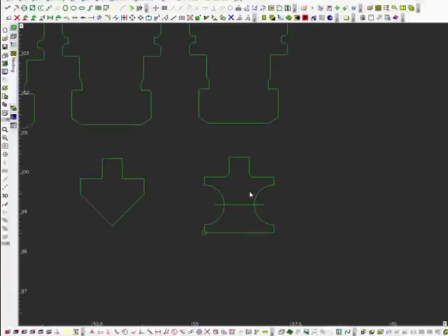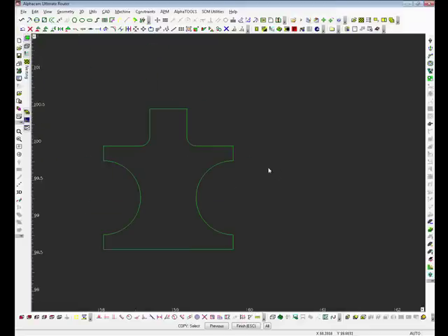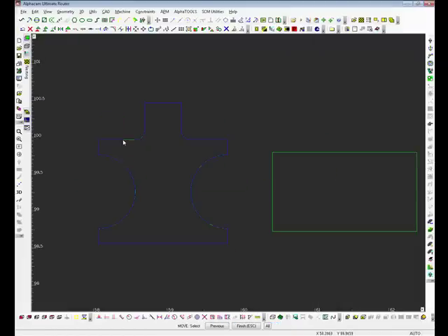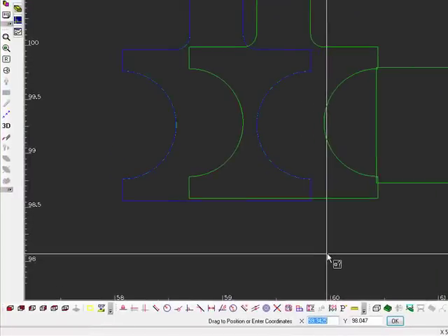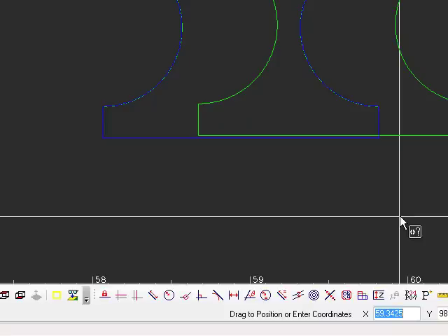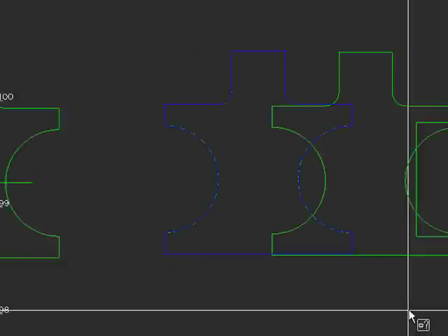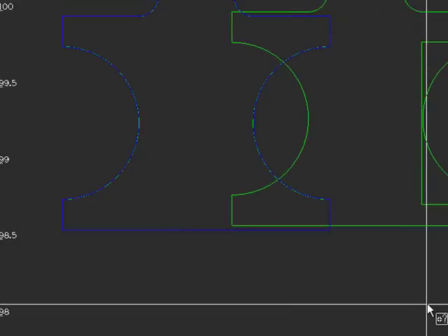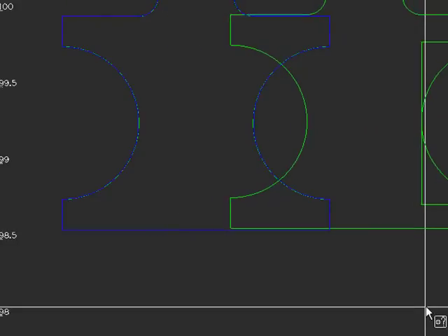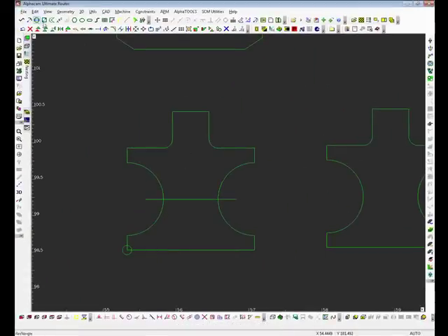Let me go ahead and exemplify this. I'm going to copy this out, and I'm going to put it on the right. And this rectangle that I'm drawing represents the material that I actually want to cut. You see, if we didn't have that line, the tool would always act right there, right on the edge of the material. If I put the line in the center, like we see over here, then that is going to tell AlphaCam that you want to work the tool all the way in there. Okay? So basically, the distance between this point